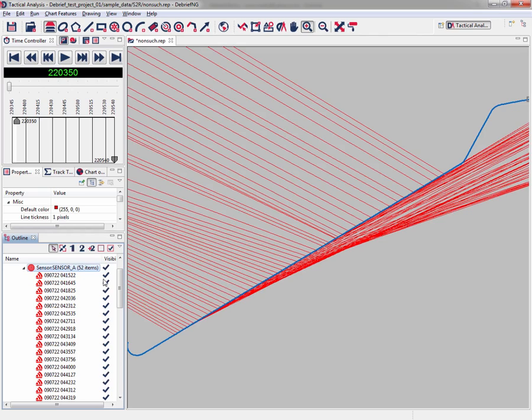Now in our data you can clearly see one bearing fan heading off to the northwest and the other towards the northeast. Now this is typical of a towed sensor, as they produce both a true bearing to the target and a mirror reflection ambiguous bearing. So what we need to do now is drop the ambiguous data. Now in this example, intelligence tells us that the actual contact is off to the northwest. So we can dismiss or drop the ambiguous data set of bearings that generally point to the northeast.